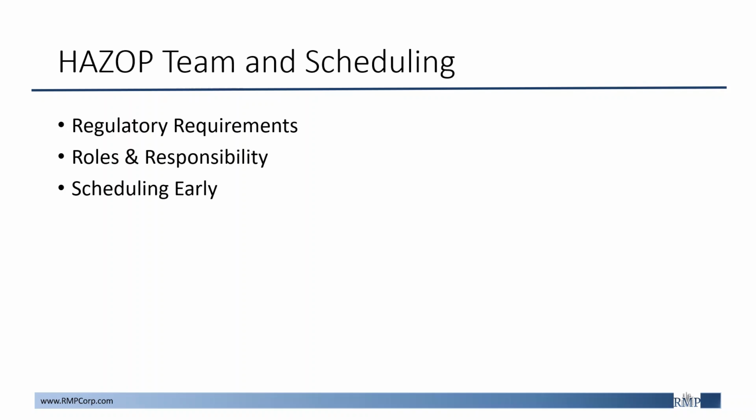But it's also important to note that scheduling early is of the utmost importance because the individuals required to be part of the HAZOP are typically some of the busiest, and their full attention during the sessions is extremely critical in the effectiveness of each session. So with early scheduling, individuals who are required to be present during a HAZOP can plan accordingly to be well prepared for the study so that the session time is spent working through the hazards and brainstorming rather than waiting on information that was not well prepared ahead of time.